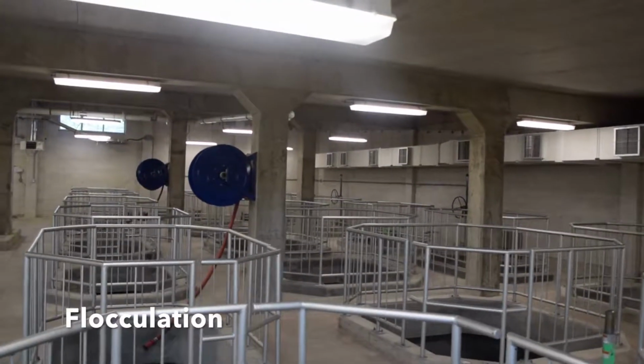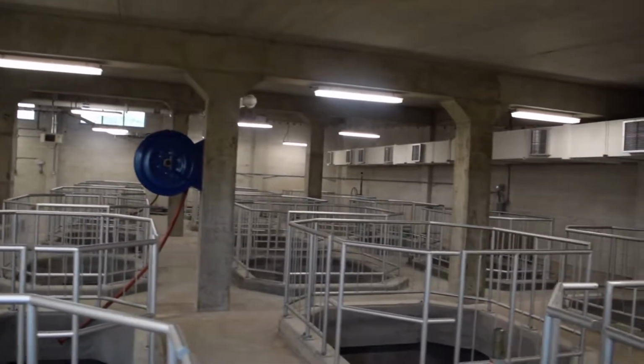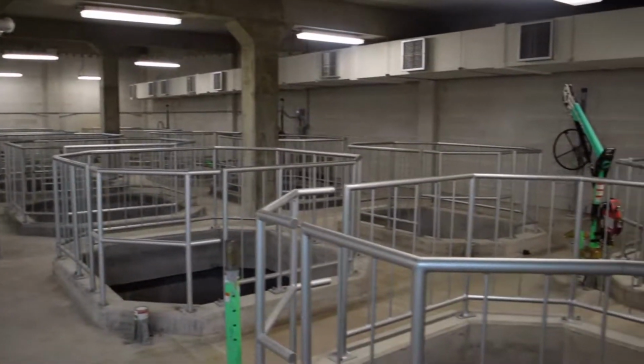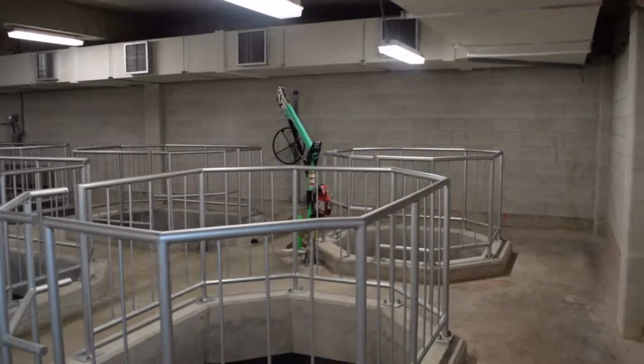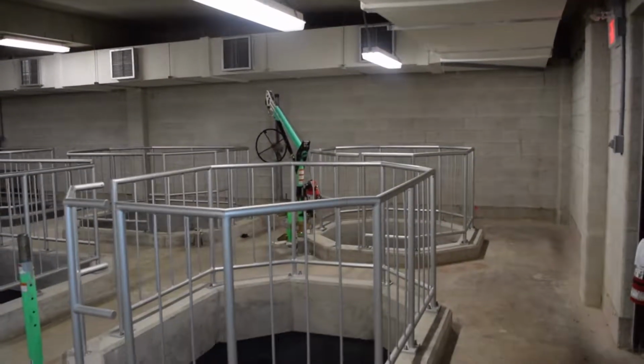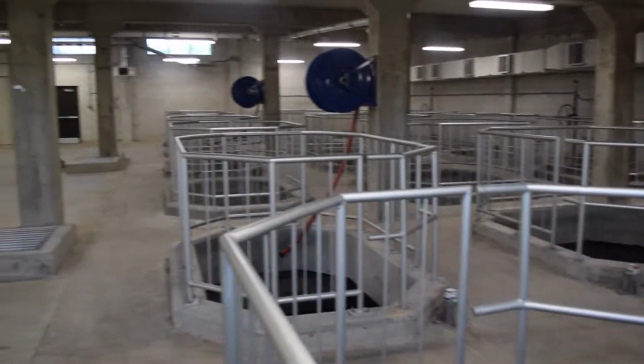After the flash mix, the next step in the treatment process is flocculation. Flocculation is a process used to form a heavier floc through a continued gentle mixing. Each of these cells contains small holes to allow passage of water from one chamber to the other.